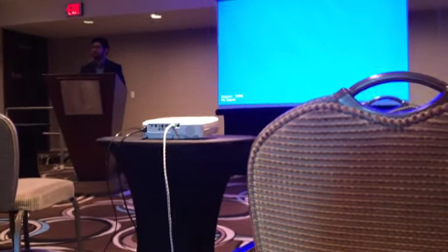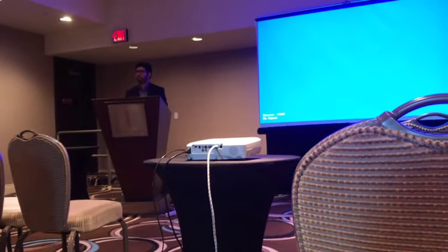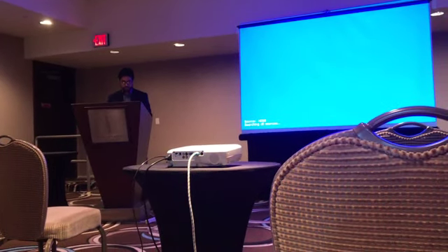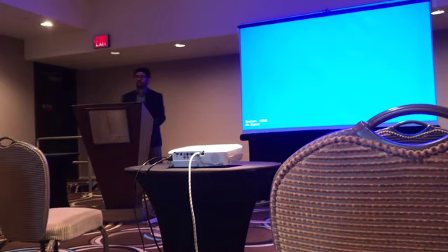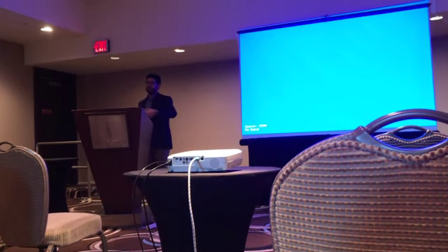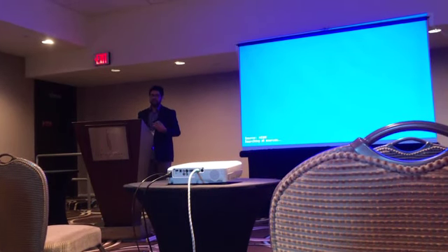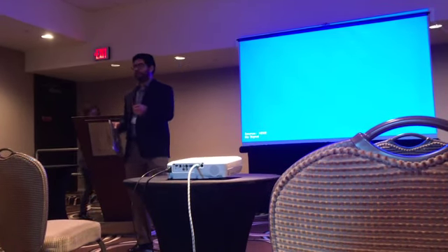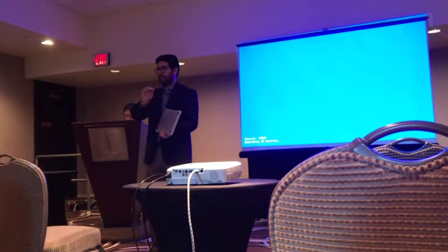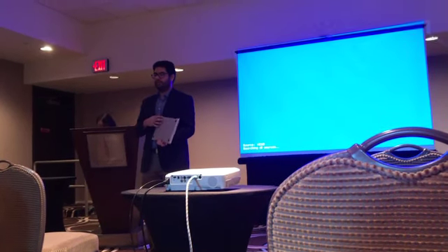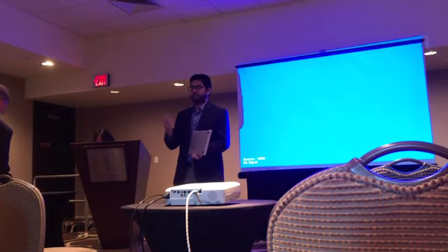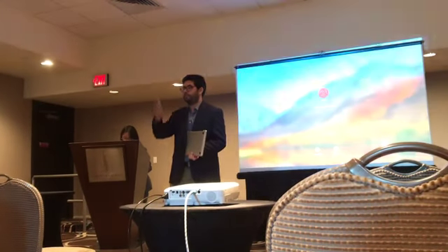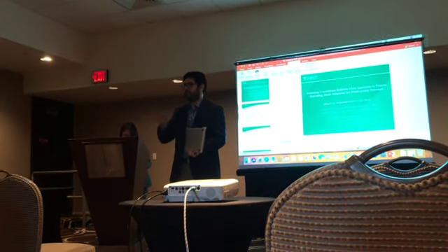Because you constrain your input to some subregion, does this constraint include a saturation constraint? No. Saturation would typically be applied after the computation. I haven't done many examples, but I have done a couple of examples, just numerically on a linear system, where I saturate one of the actuators. Obviously it degrades the performance, but nothing catastrophic happens. It still works. The computed output is always going to lie in the range space of whatever matrix you choose.